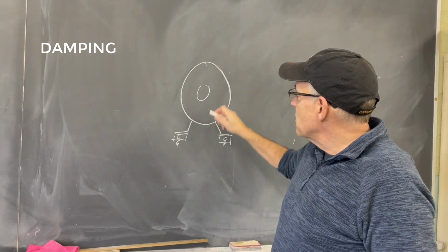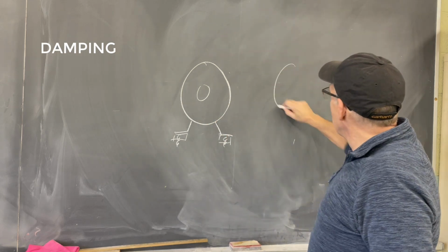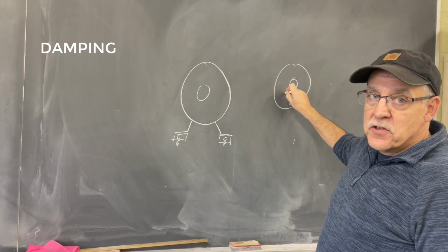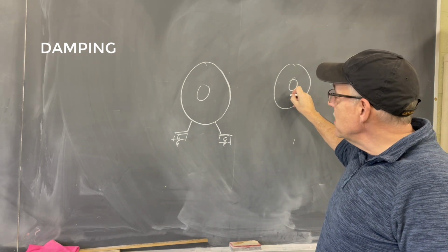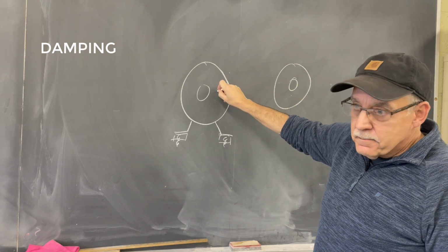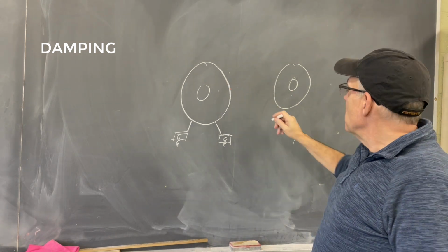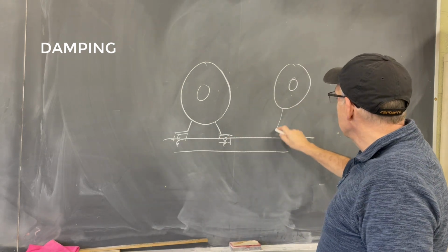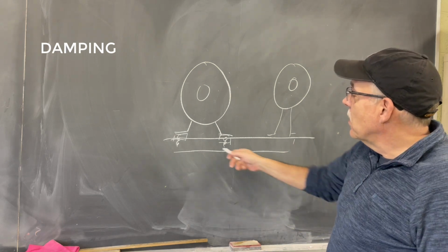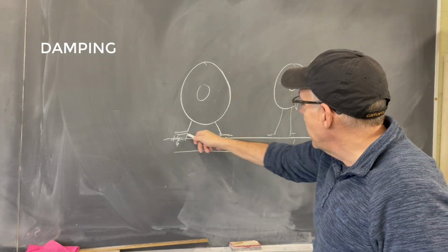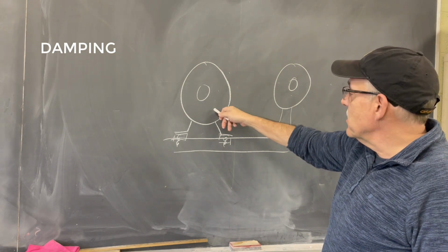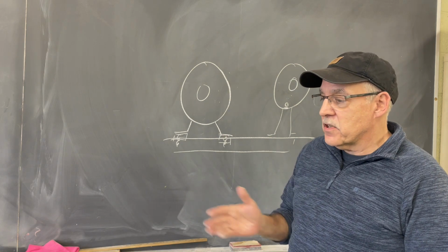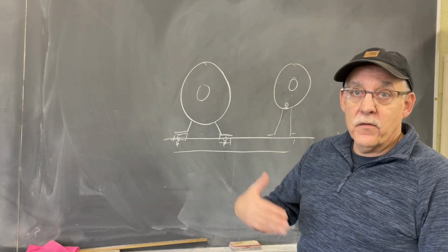They're also separating this piece of equipment from other pieces of equipment, so that the vibration from this piece of equipment doesn't cross-influence another piece of equipment. A lot of times you'll see a bunch of pumps on a skid, like so, please forgive my drawing. They'll be isolated with these little damping pads underneath, so they're isolating the vibration from this pump to this pump. All those are factors that we consider when we look at how much something will vibrate.